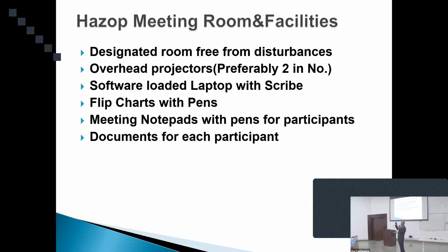Then it comes to the process flow diagram. Next level. The same process which is written is shown in a diagram. That's called the process flow diagram. Okay. Then comes the piping and instrumentation diagram. That is the next level, which gives you all details about your process, control valves, instrumentation. Everything is given in that P&ID. Okay. And after that, the P&ID also comes with the safeguards. Like control narratives, interlocks, trips, alarms. It's all the description, all the documents.